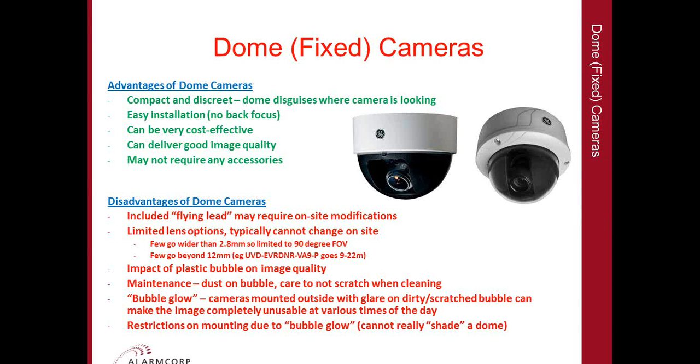And also few domes go beyond about 12 millimeters focal length. Now, in the Interlogix range, there is an option which goes from 9 to 22 mil in focal length, but I have not yet really seen a dome with a longer focal length than that. So if you do need to have a very specific or narrow field of view, looking at an object that's further away, a dome may not be the best choice.